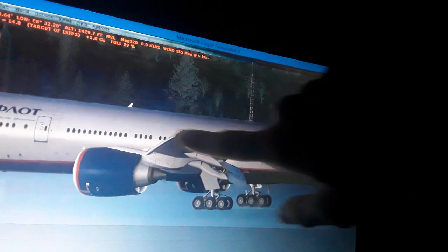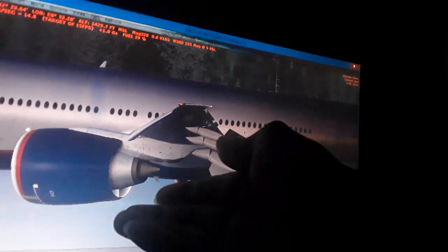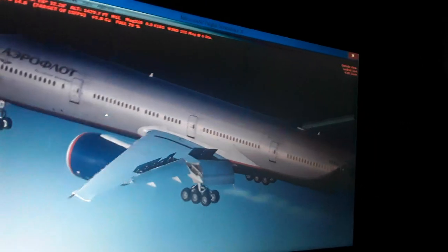So you can see the bottom surface of the wing is more flat, generally speaking. So as the aircraft accelerates forward, the airflow of the air mass moves slower below the wing because the wing is more flat, so it pressurizes the aircraft wings up into the air. You have positive air pressure, higher air pressure below the wing, that pressurizes the aircraft weight up into the air.